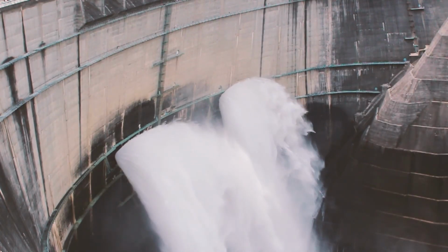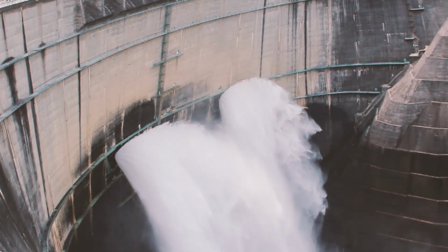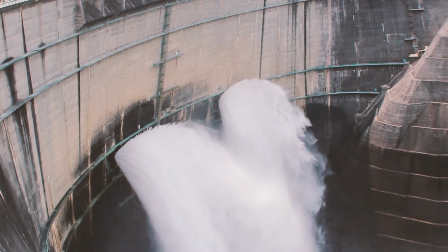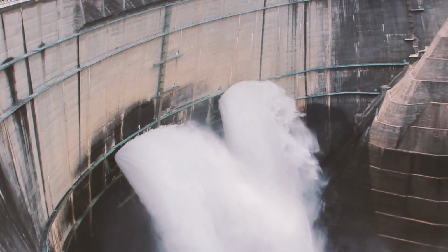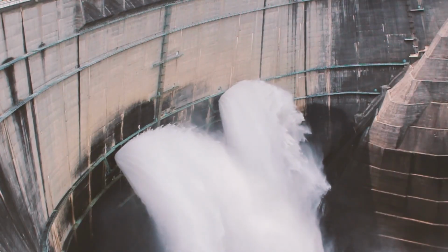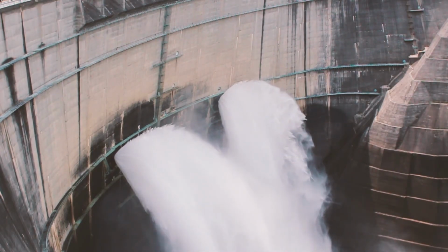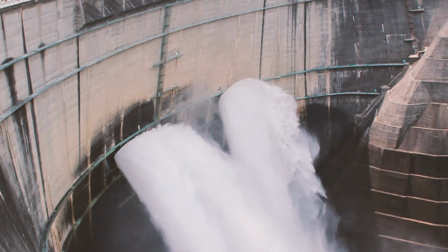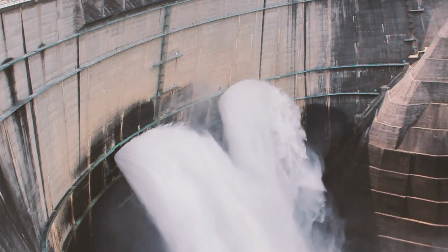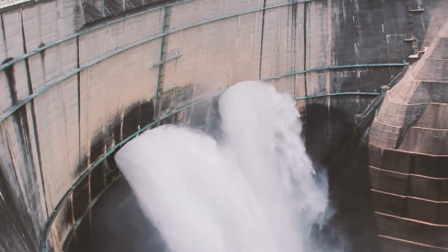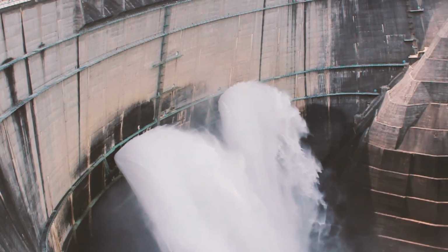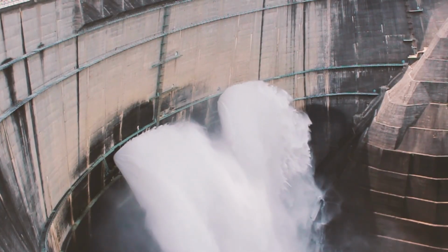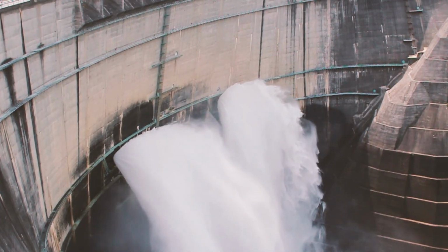But before we size a spillway, we must first understand what problem the spillway is solving. A spillway is a safety valve of a dam. Its simple job is to allow all the excess water to leave the reservoir safely. Without a spillway, water will just rise until it flows over the dam crest, a scenario commonly called overtopping, and it's extremely dangerous for most dams. Because of this, the spillway must be able to safely pass the extreme floods.